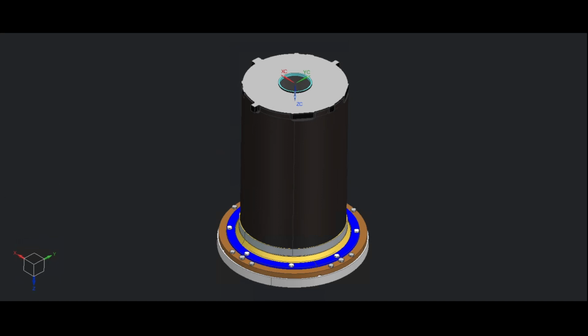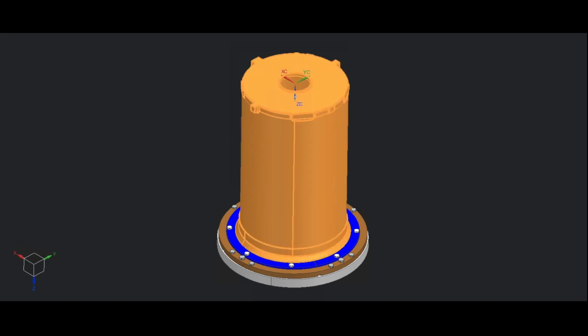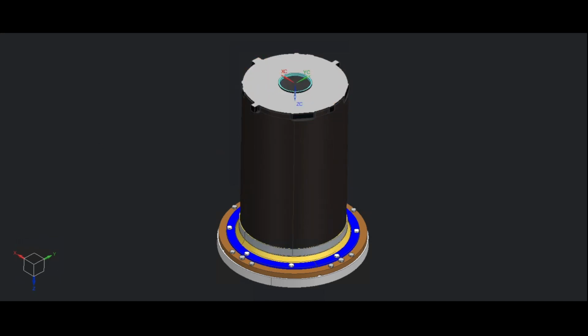We have the optical payload itself, highlighted now in yellow. This is bolted down to an interface plate using a clamping band and two clamping rings, 1 and 2. And the interface plate is in turn bolted down to the shaker table, which is not present in the model. Between the two clamping rings and the clamping band, we have 8 bolts with hexagon head. These ones here.